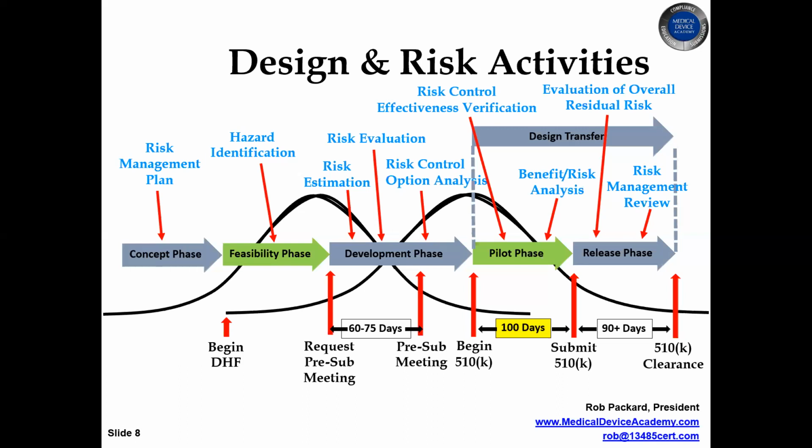It's not just I approve the drawing. That's design freeze. It's all the things that occur from the time I approve the drawing to the time that I commercially release. And there's a lot of things to do there. And that doesn't mean you're not going to change any of your drawings. You might update drawings that you froze, but they might not be a change in spec. They might be, we've identified the vendor, we've added an inspection criteria. Those are the kinds of changes we typically see on outputs during this design transfer phase. So you approve the spec, but you didn't approve all your inspection criteria and the vendor and where they're going to come from and how they're going to be shipped, what the lot sizes are going to be. All that information is part of design transfer.